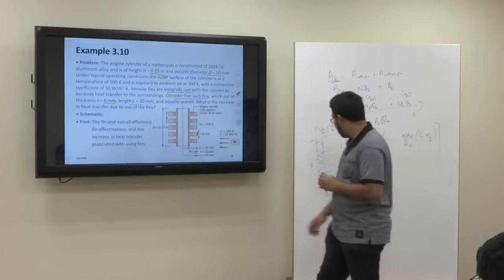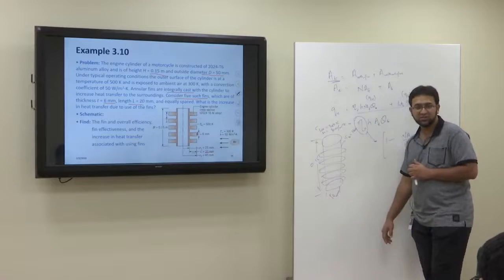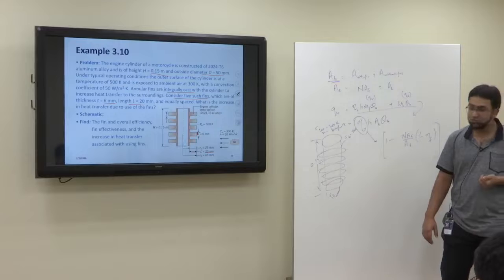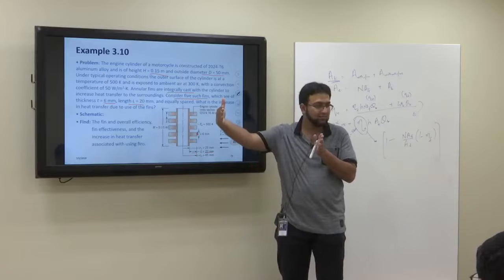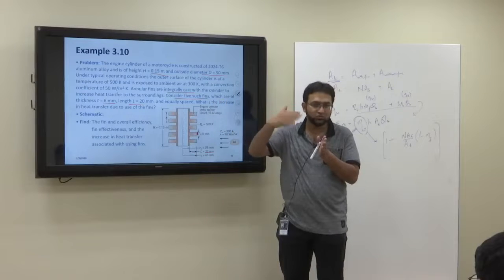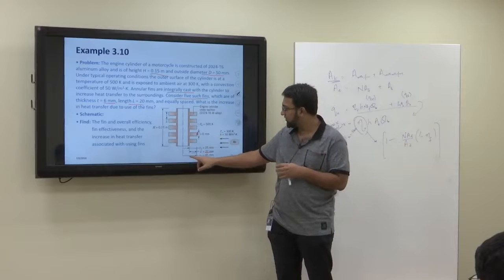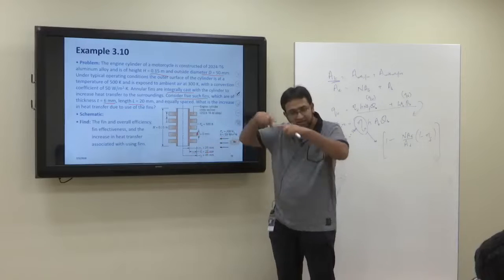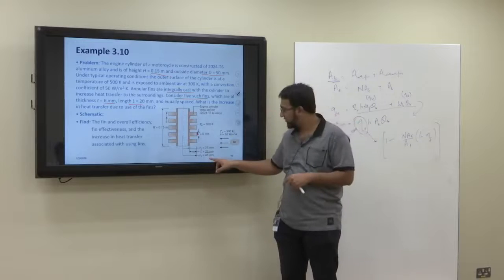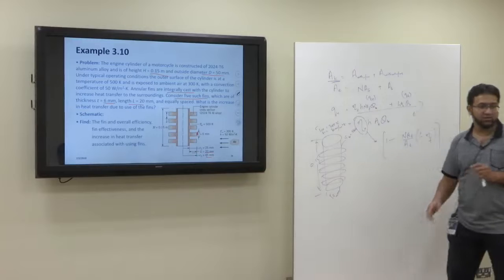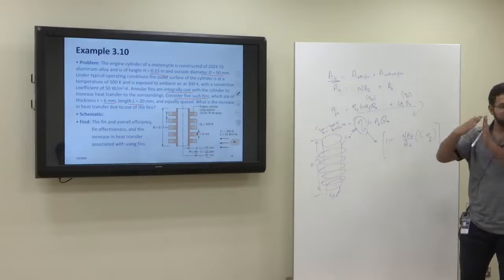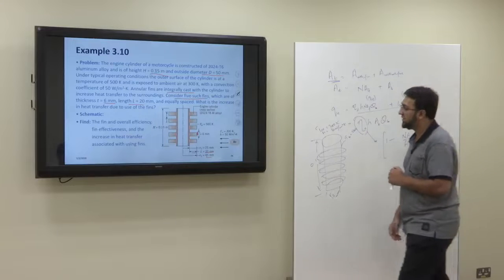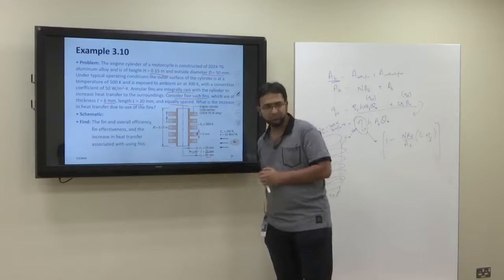Okay, so look, the thing is that if the diameter is 50 millimeter, then the radius becomes 25 millimeter. So 25 millimeter is the outer radius, and then after that the length is extension. So it's 25 plus 20. So the radius at the outside of the fin becomes 45. Is it clear? Sorry, 25 till the base, then extension 20. So 25 plus 20 is 45 radius. Is it clear? And the thickness is 6 millimeter, and they are equally spaced.